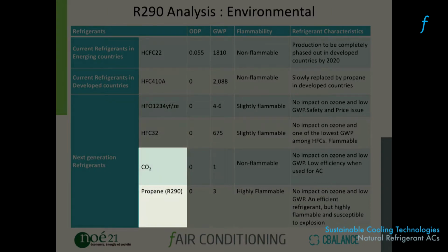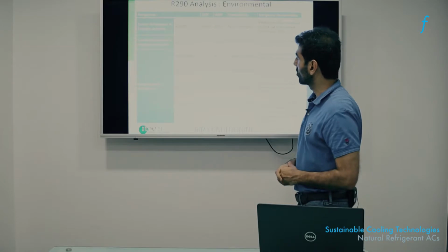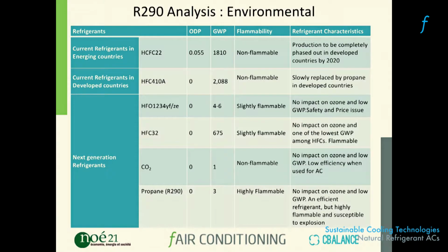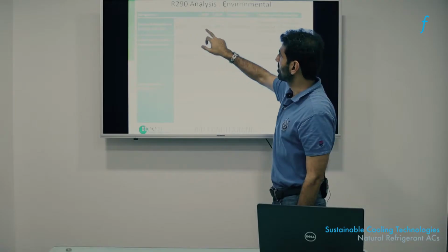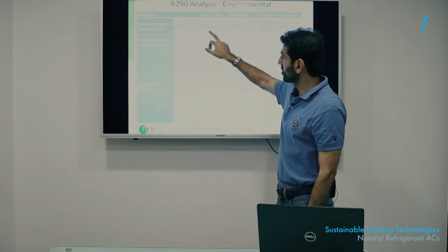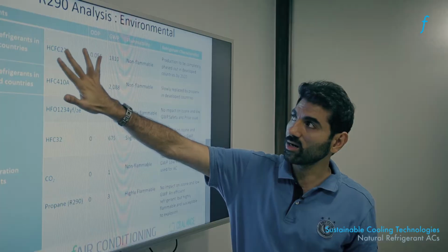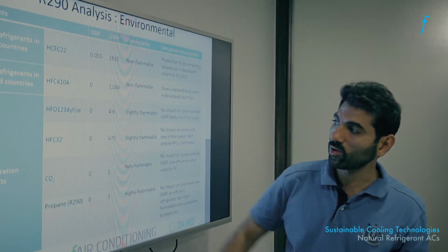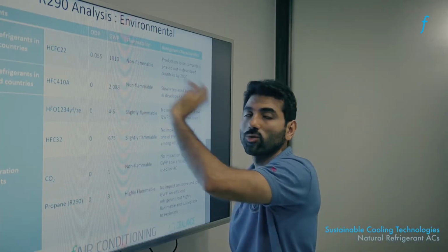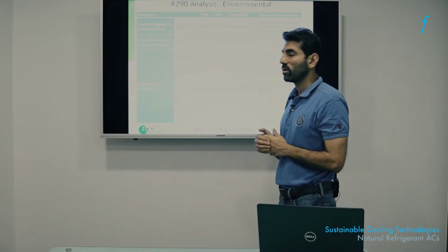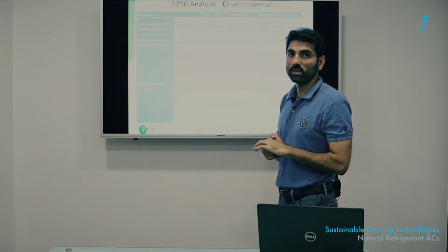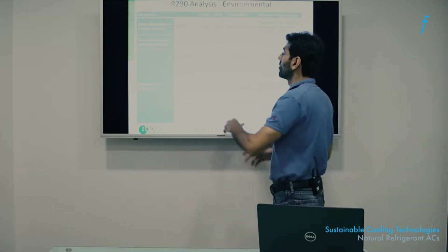The first attribute that we can pay attention to is the ozone depletion potential. Now, the ozone depletion potential of R22 is not zero. This is the one thing that differentiates this current refrigerant from all the possible alternatives. So, of course, this has to go because the ozone issue can re-emerge if we are not safe and we act recklessly as a community.